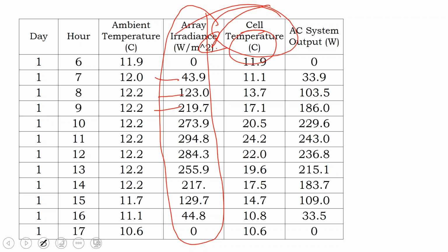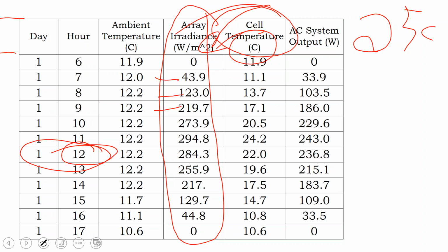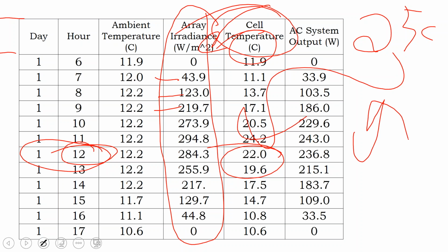And the surface temperature, we talk about standard test condition, what the module is listed at, and that module is listed at a 25 degrees Celsius standard test condition. And what we can see on this is probably for December or January. And what we see is that on January 1st, there's a year column here. It's probably for January at high noon. Our solar module is getting up to its listed temperature. And so you might say, well, what is my solar module getting up to in the summertime? That information is on PV Watts, and you can use that to do your performance derate calculations. You can find out your maximum system power.